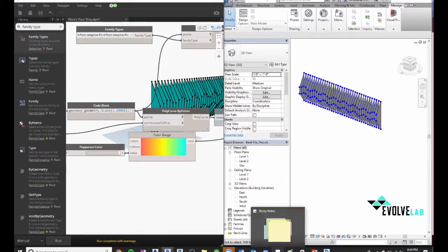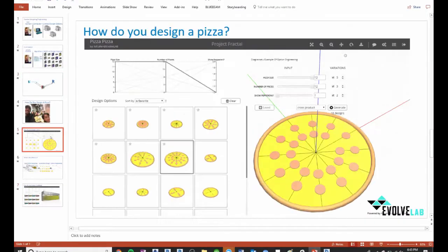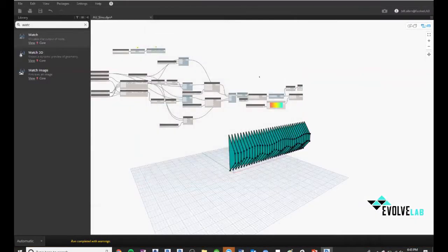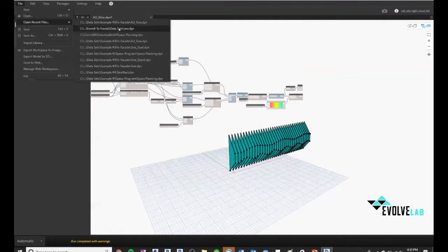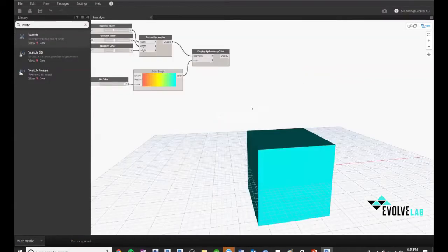Questions about the process, going to Dynamo, to Fractal, to Revit, optioneering. Yes, sir. So let's say on your box example in Fractal, if you wanted to have a column for the floor area that we're building, maybe total surface area, can you add an output? Is it somehow calculated from what's generated? Yes, absolutely. So trying to grab area from the box example, you can absolutely grab area.